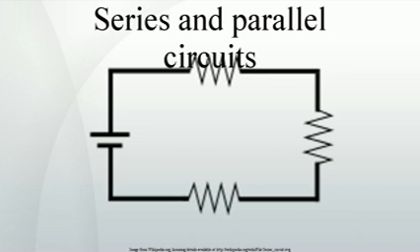If the 4 light bulbs are connected in series, there is the same current through all of them, and the voltage drop is 1.5 V across each bulb, which may not be sufficient to make them glow. If the light bulbs are connected in parallel, the current through the light bulbs combine to form the current in the battery, while the voltage drop is 6.0 V across each bulb and they all glow.